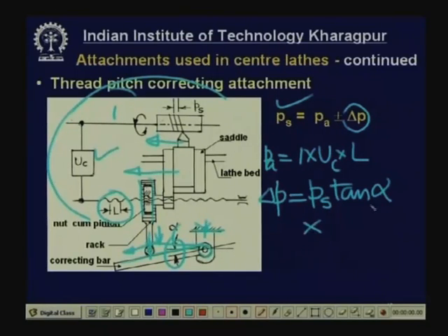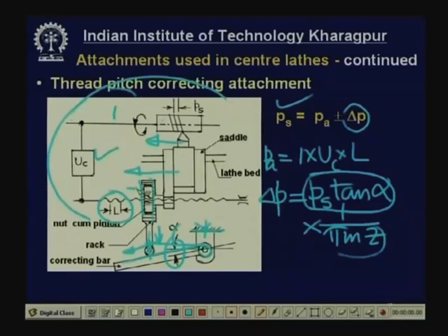That will be this divided by pi m z, which is the perimeter of the pinion. So, this will be the amount of rotation of the pinion because of linear movement of the rack this much. Because of this rotation of the pinion, there will be some movement effectively on the lead screw.